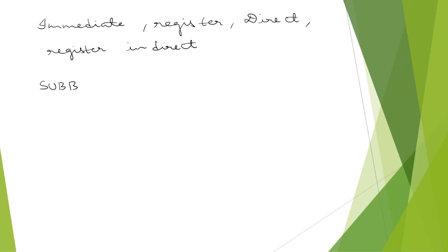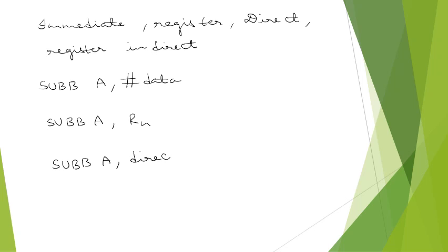SUBB A, #data for immediate addressing mode, and then SUBB A, Rn for register addressing mode, then SUBB A, direct for direct addressing mode,